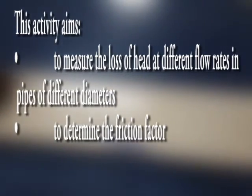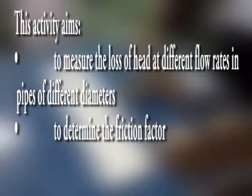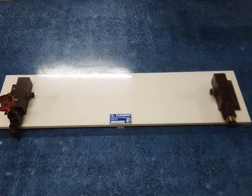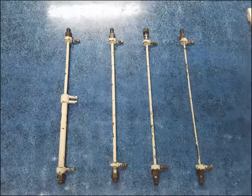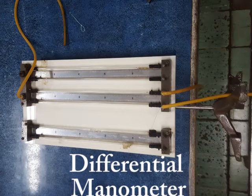This activity aims to measure the loss of head at different flow rates in pipes of different diameters and to determine the friction factor. Apparatus and supplies. For this experiment, we will be needing a pipe holder and a set of pipes. We will be using the 5mm and the 7mm pipe. The differential manometer will determine the difference in pressure and head between 2 points. Now we are ready to begin.